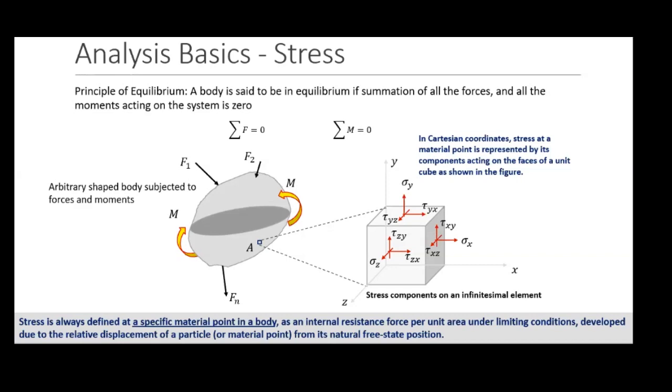And as your factor of safety increases, doesn't your cost usually increase? The reason, as we all know, is that a higher factor of safety increases the weight of the material. When somebody says it's over designed, it is basically that you are using a higher factor of safety, which means you're putting in more material. And when you're adding more material, you're adding more cost, and everything else goes high.